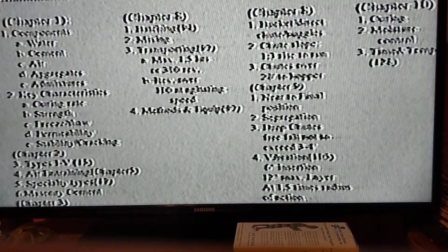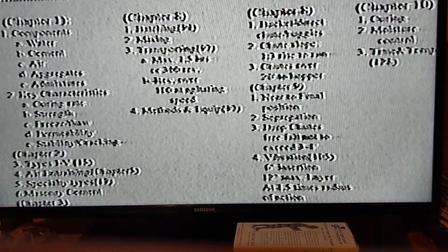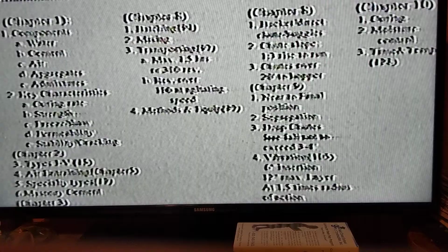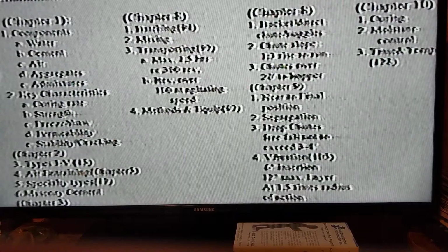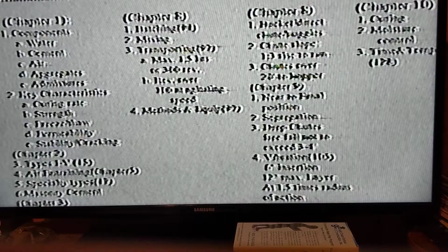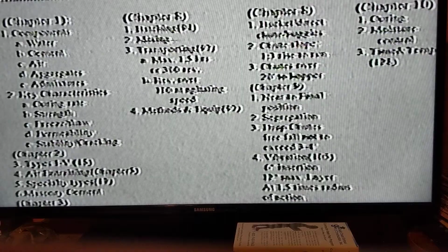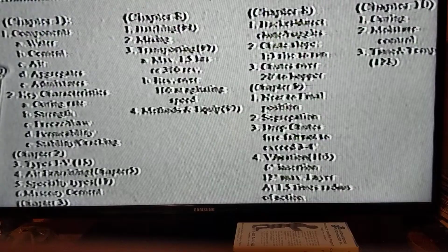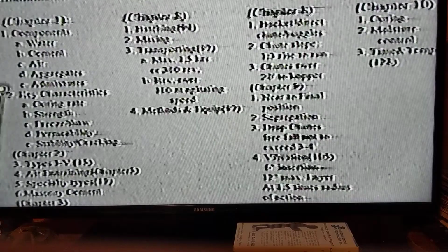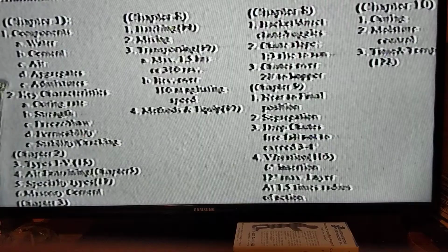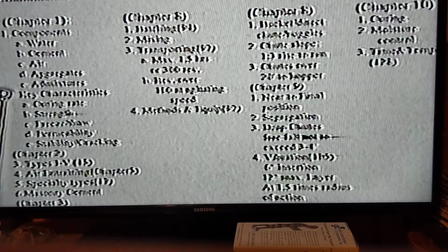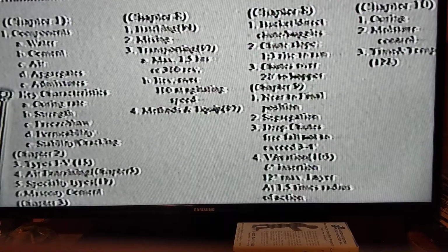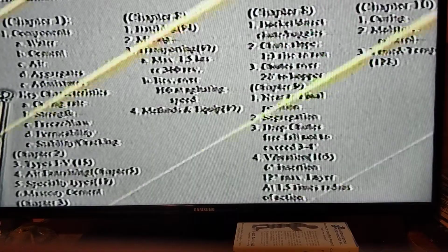Now, the terminology that's used is segregation. You don't want the concrete to segregate. You don't want its parts or components to fall apart, because then you will not have a uniform mix. Now, regardless of the type of cement that's used, the basic components of concrete are water, cement, air, aggregates, which are big and little rocks, and then admixtures, which are additional chemicals which are introduced to the milkshake to provide specific qualities to the milkshake.